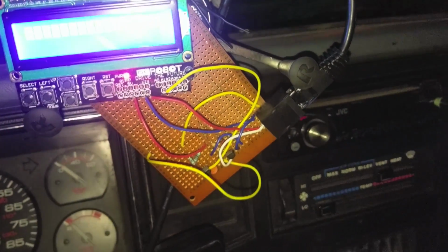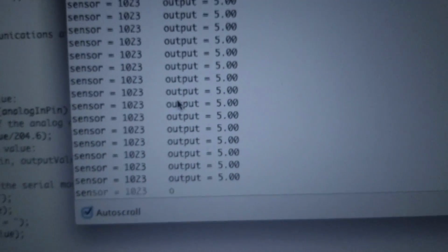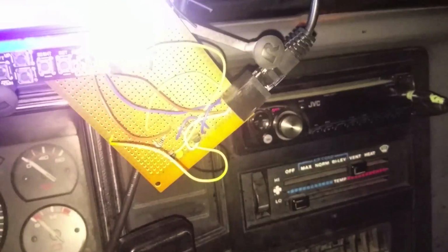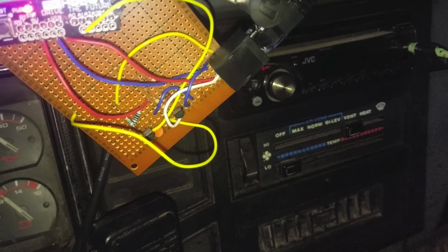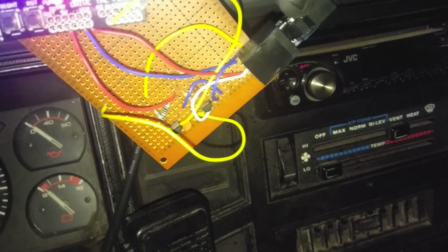Okay, so I tried hooking up the signal to our pen, and we're not getting nothing. We're only getting 5 volts, which means that the transistor is never being switched on. But if I check from the input from the TCU TX pin to ground or positive, I don't remember which one it is, I still get that signal. So we're still getting the signal properly, it's just not being switched properly. So yeah, I'll have to look into that. So it might be more of a hardware issue.